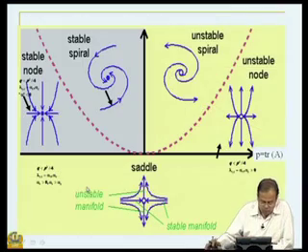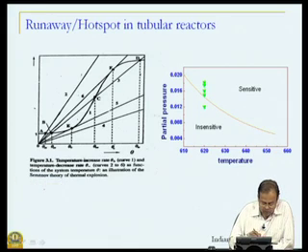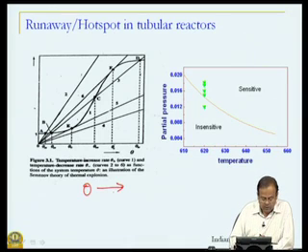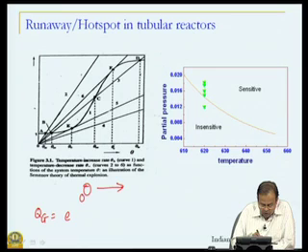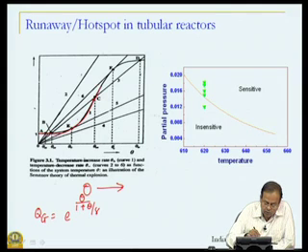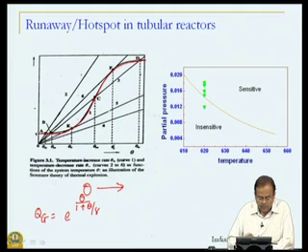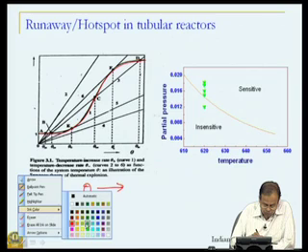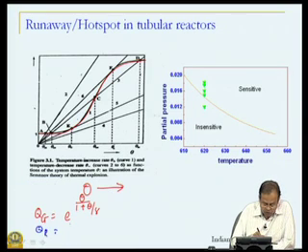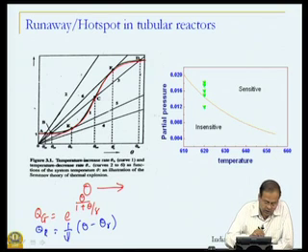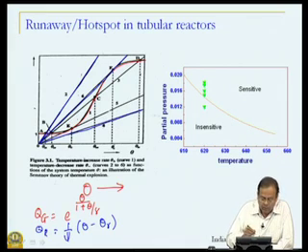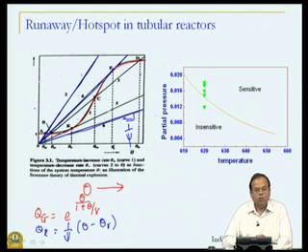What we are seeing here is temperature theta on the x axis and the function Qg, which was e raised to theta by 1 plus theta by gamma, which is shown by this red line over here. Okay. And function Qr, which is 1 over psi, theta minus theta r, graphically will look like straight lines, which are these different lines that we see with the slope 1 over psi. So, there are various different lines, but the slope of this line is 1 over psi.